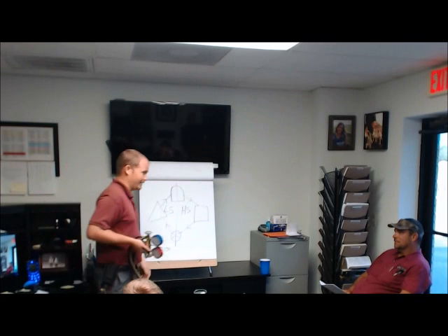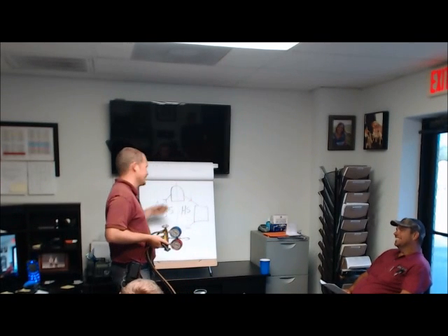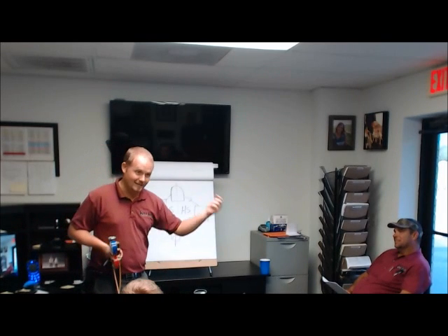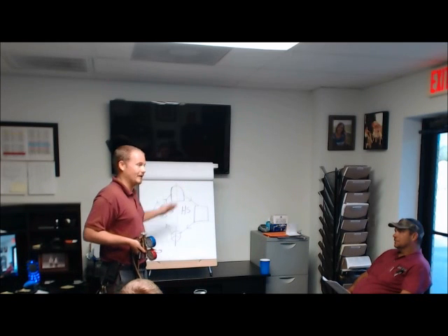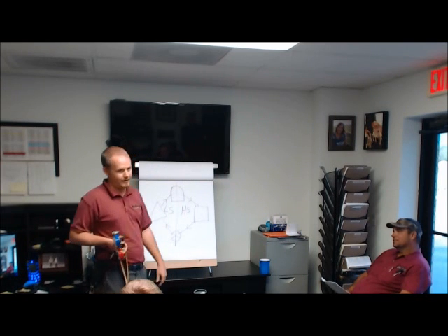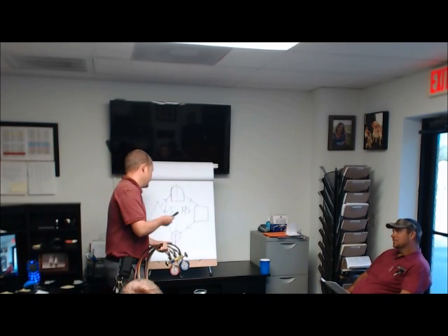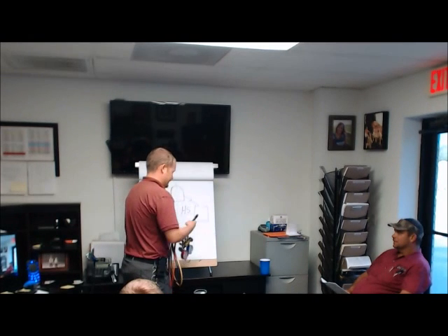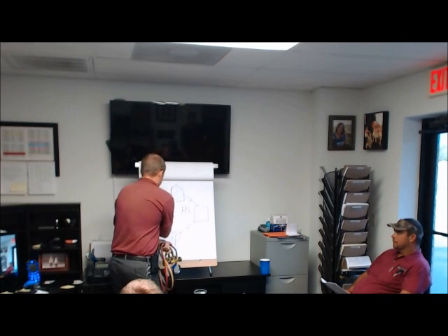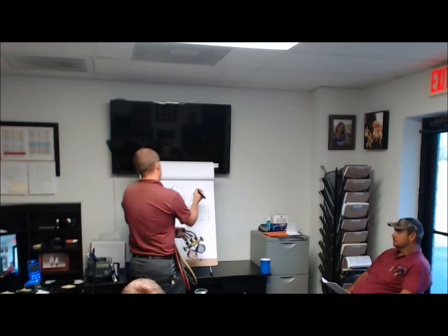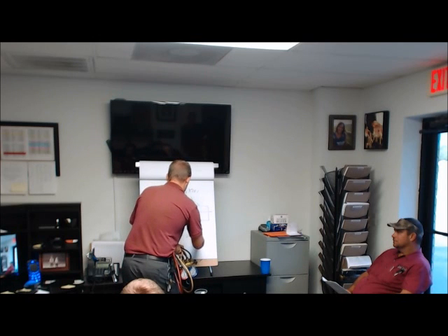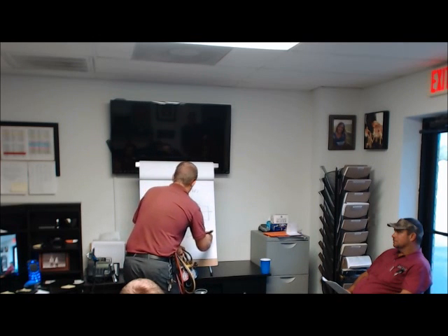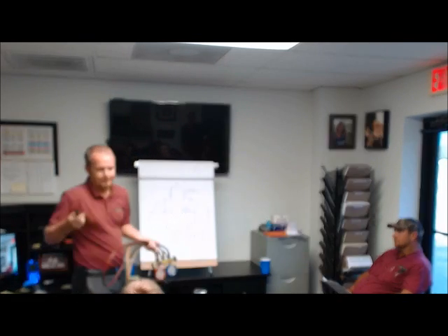All right, now here's the next thing. Discharge line, liquid line, expansion line, suction line. Now write in the states. Now split it in half based on the state of the refrigerant. Now split it in half based on high side and low side, because you do it the other way here too. So this is low side, this is high side, and then this is the vapor side. This is the liquid side. It's actually saturated liquid as it comes out the other side here.